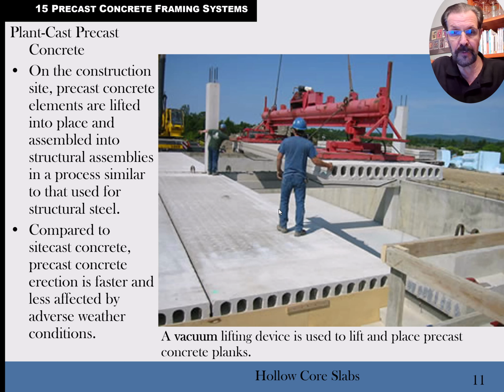Whereas a lot of times when you're picking up these hollow core slabs, they have a lifting clamp that grabs a hold of the keyways on each side. A little kind of a complicated key jointed system on the edges, in order to grab a hold of the thing. Whether it's a vacuum pump or grabbing it by the keyways, you don't want your toes underneath that no matter what, because there's always a chance these things can drop. The hollow core slabs are used to build floor systems, precast floor systems.